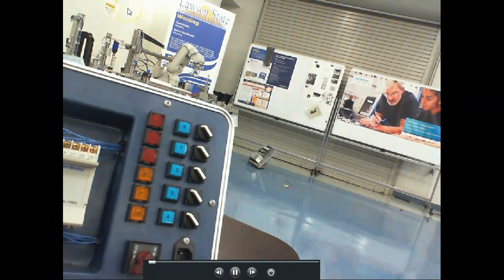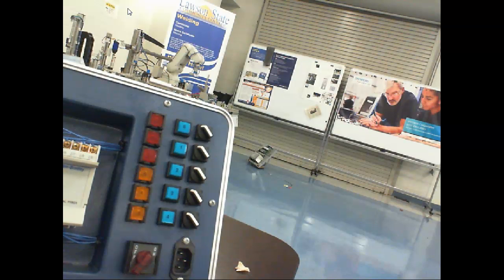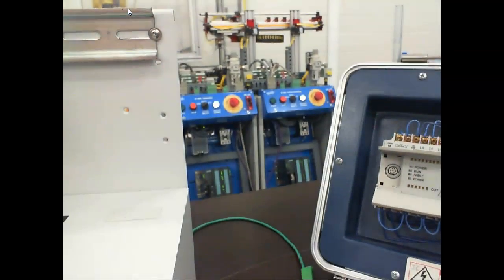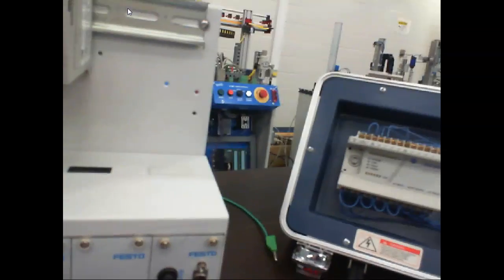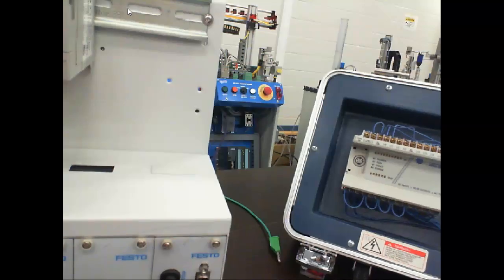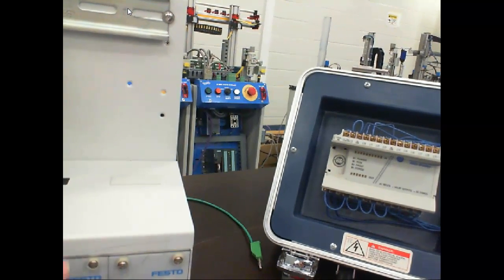The only problem is that none of these lights would work, because all those lights are 120 volt lights. So that would be the biggest problem for me. Now it would be a lot safer, but I'd have to go over there and buy a bunch of 24 volt lights and replace those, which would be good. Or I could unmount it off this guy and move it over here and run them off 24 volts. So this is the same thing. It's got relay outputs. Here we're taking DC and running the commons. So here we're using DC on the actual outputs coming out of the Edu-trainers.